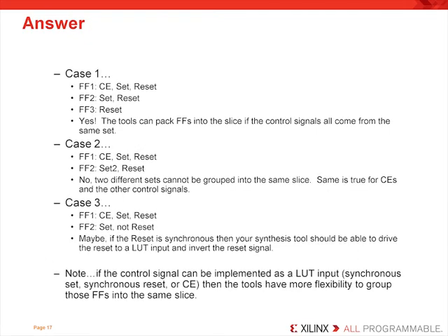Well, here are the answers. The first case, recall the situation with the 3 flip-flops. Yes, the tools can pack these flip-flops into the same slice because the control signals all come from the same set. Case number 2, where we had a different set signal but the same reset, no, they can't be grouped because 2 different sets cannot be grouped into the same slice. The same is true for clock enables and other control signals.